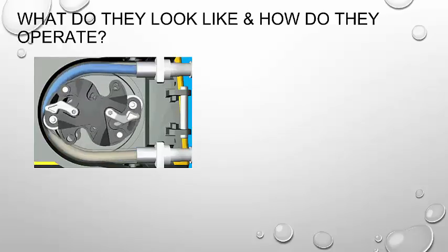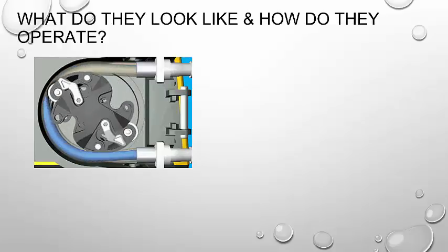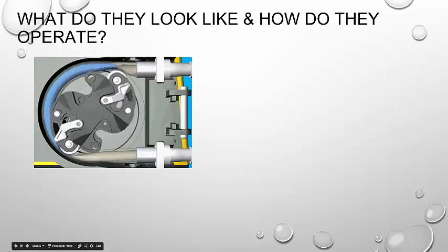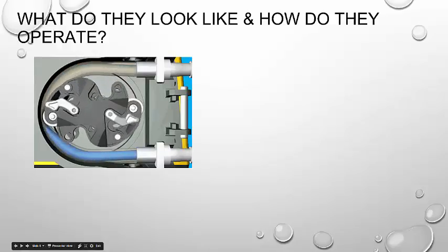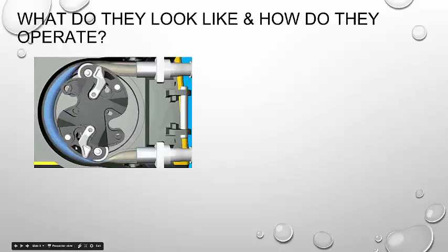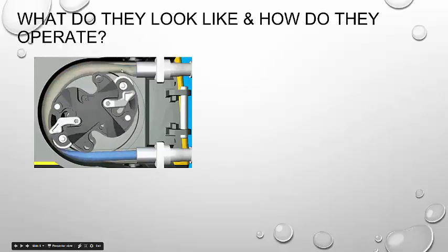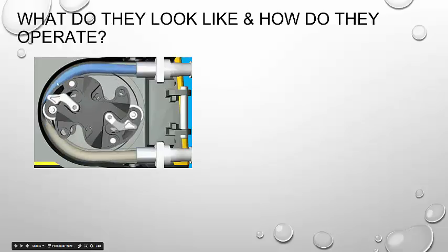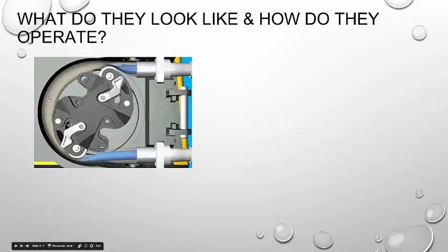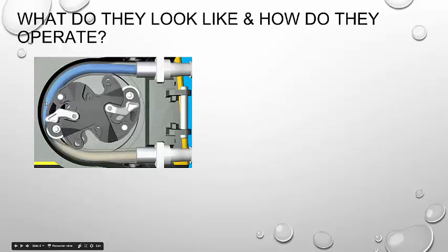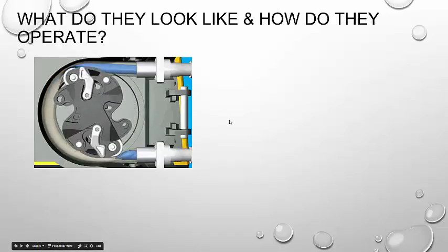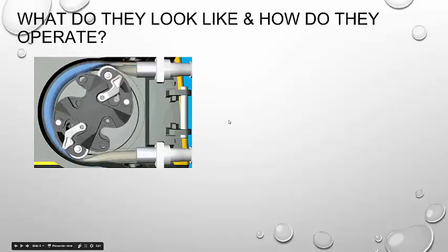If it is not, it's going to be a displacement pump. And hopefully by now you notice there is only a specific volume of water that is being pulled around this pump. As you can see here, this is going to go up and around, and we're applying energy just to that volume of water. So hopefully by now you have answered this question. Is it a displacement or is it a dynamic pump? And I hope by now you figured out that it is indeed a displacement pump.